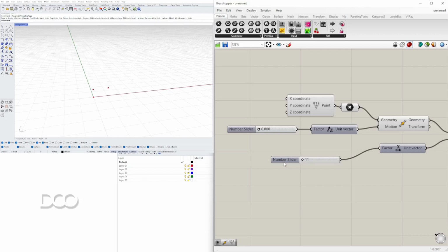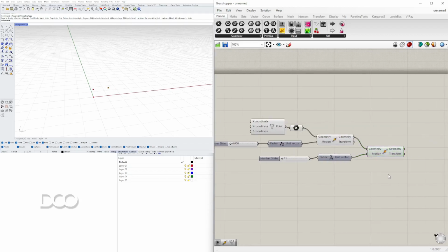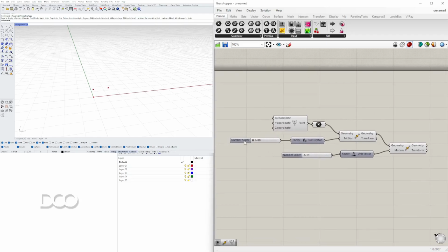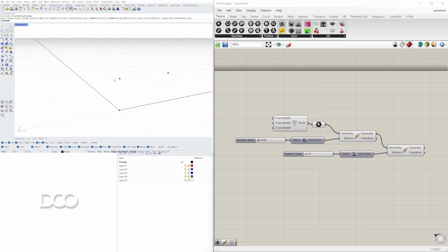This way we don't go any smaller than 11, we don't go any longer than 20, and we're kind of keeping in mind some of the minimum and maximum so we don't go past those. Now this is just using a regular slider. There are other ways we can achieve this, but this is basically what we need to create a basic set of stairs. But in my case, I want to create a nosing here because typically that's what you would have on a set of stairs.